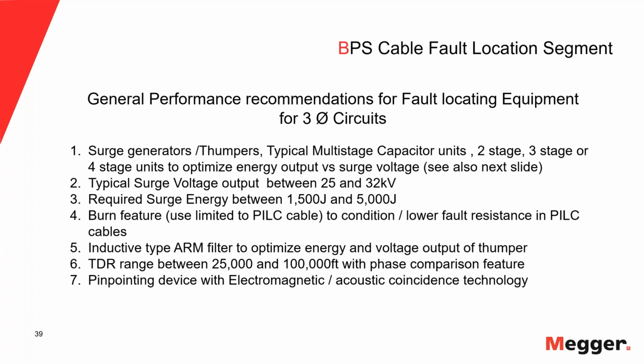So the current itself cannot damage the conductor. But when you have a low resistance fault, it will do a lot of damage there, okay? And that's the whole intention. It should condition the fault so I can thump it, okay?